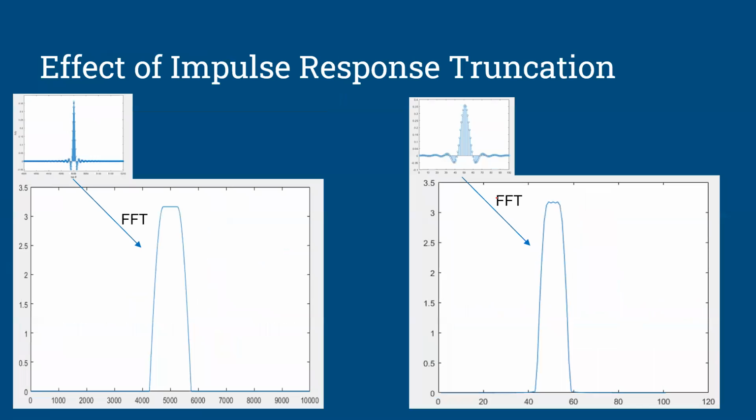Okay, so we can see how that actually looks in the frequency domain. If you take the FFT of both of these impulse responses, you get these. The one on the left is the better approximation, and as you'd expect from a root raised cosine, the frequency response decidedly goes to 0 at some point, which is right here, and after which it's 0 for all frequency.